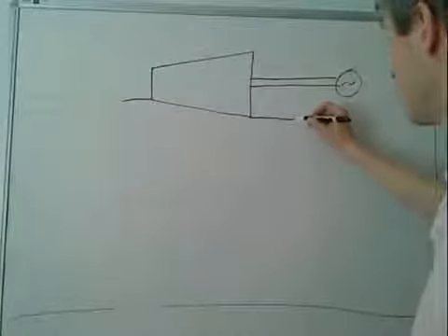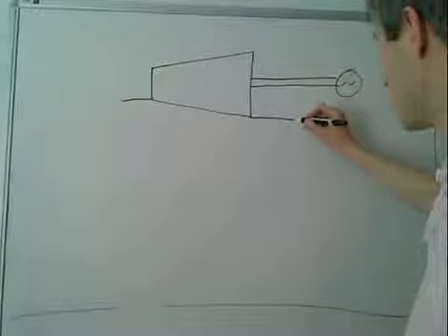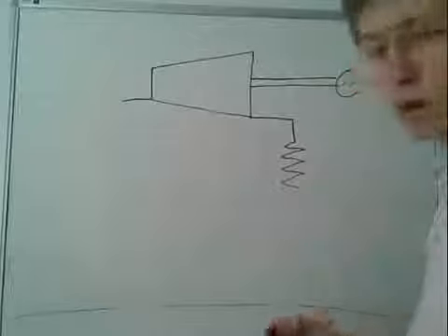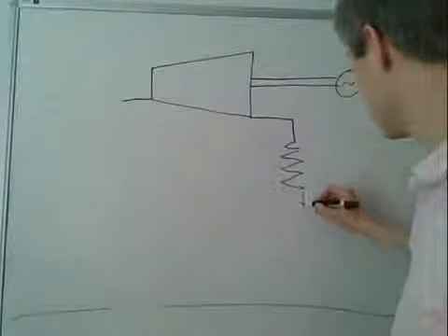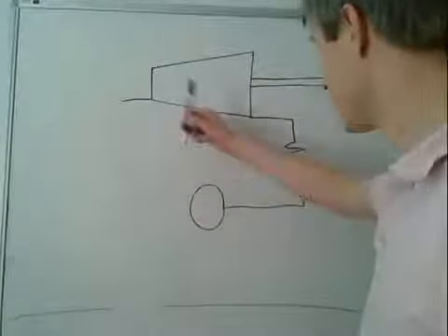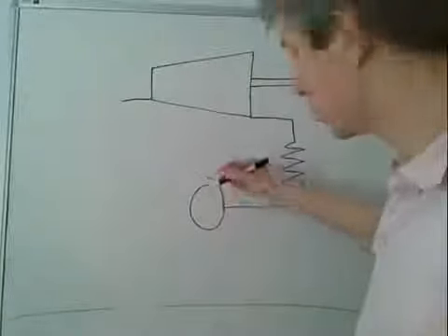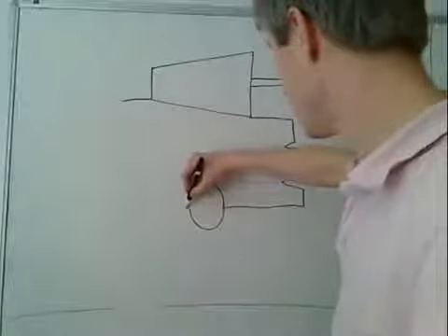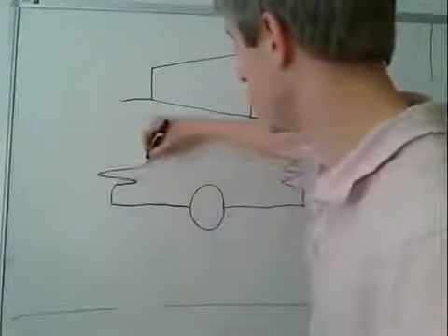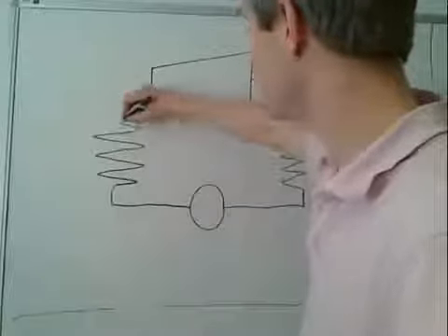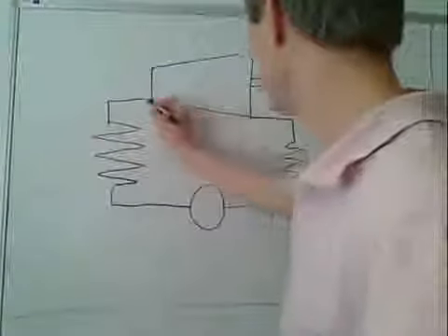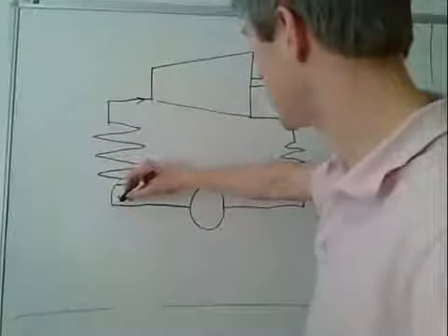This low pressure, colder steam comes out and goes into what we call a condenser, where it's turned back into water. This water goes into a pump to return it to the original pressure, but it's only pressurizing water now, so it costs less energy. And we put the water into a furnace or a boiler, it gets turned back into steam, and so we should maybe put an arrow on here so you know the direction of flow.